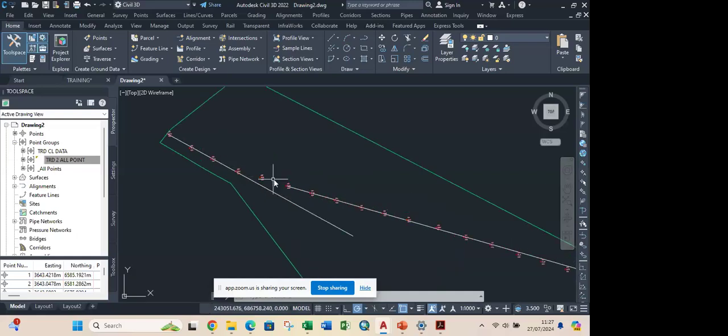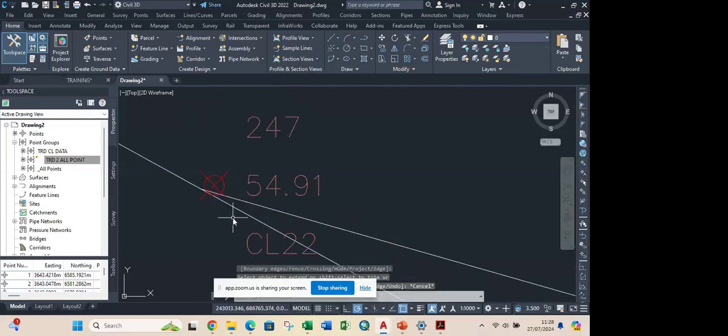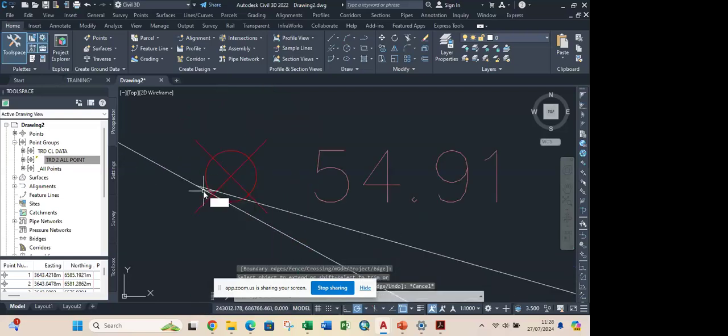So if you're done with this now, the next port of call, I'll now do my extend command. Normal extend in AutoCAD, extend this one to hit this one. So the next step, I'll now do a trim command. So I will trim.